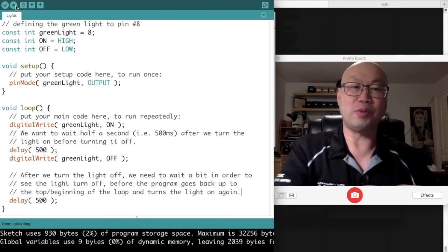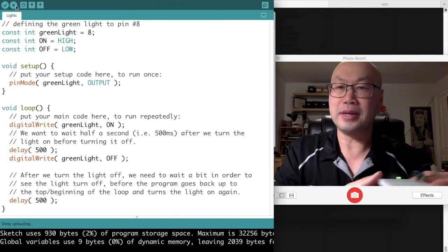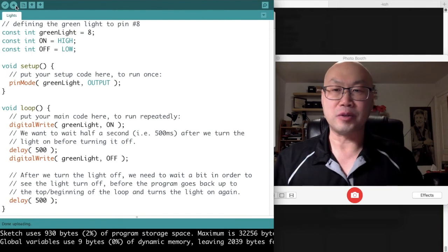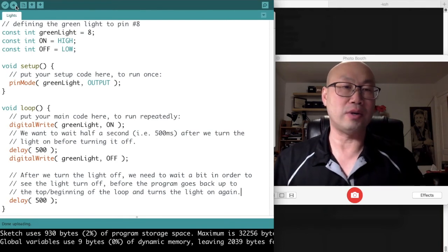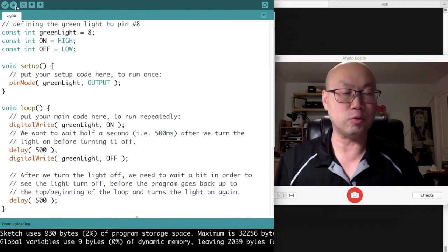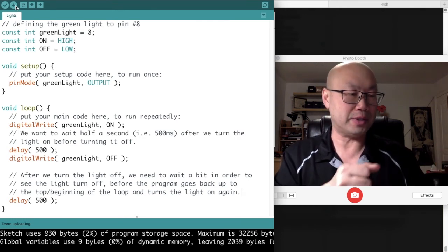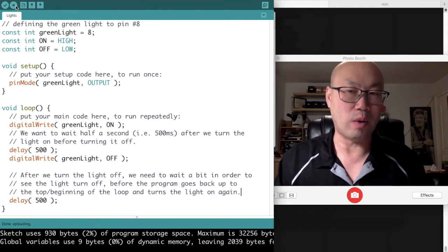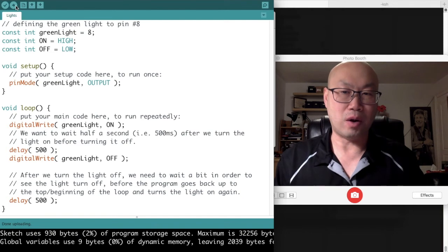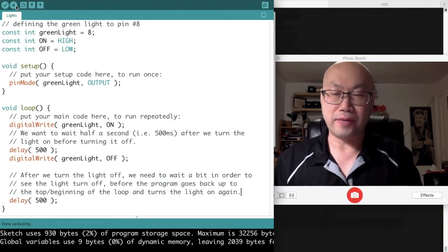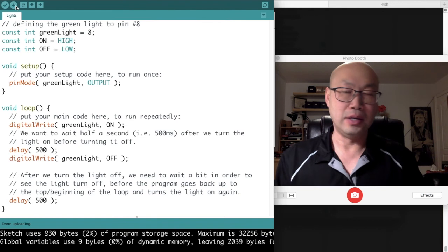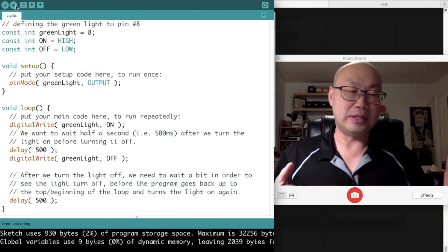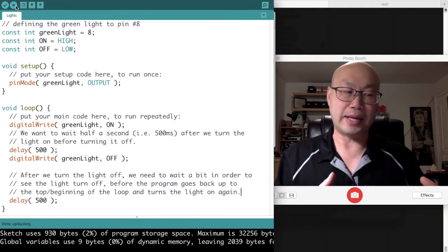Some of the nuances that we see in programming are that we need to iron out our logic when something isn't going right. This is the difficult thing about hardware or Arduinos: it can be a hardware problem, something wrong with how we connected the components together or our wiring, or our program is wrong. We know our program was wrong in the first place because the light actually turned on, so we know the connections were right. If the light never turned on, then we would have to be worried: is it the actual connection?